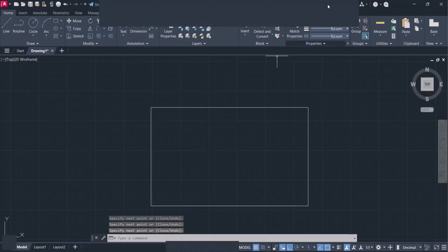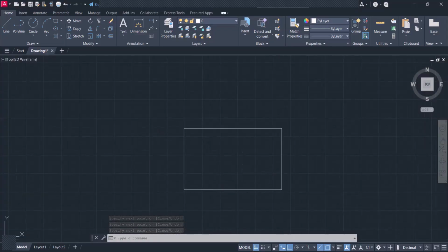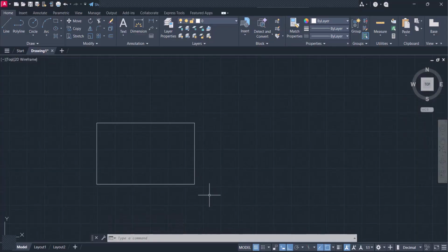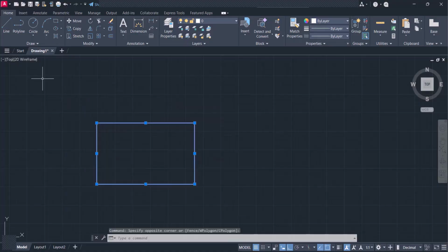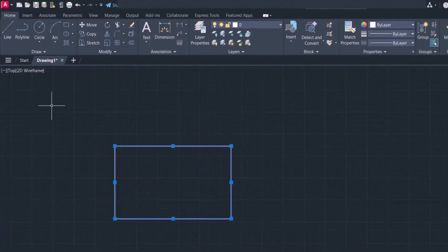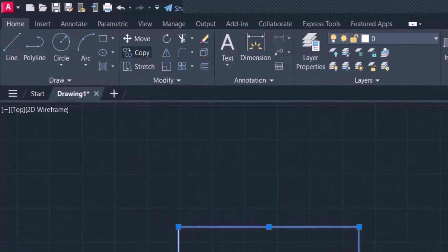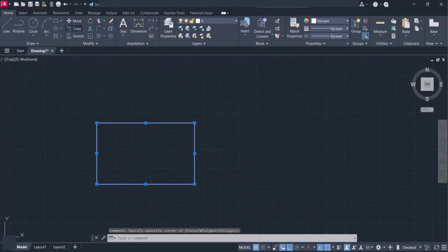So I'll need this rectangle twice, but instead of drawing it twice, we could just use the copy command. I'm going to left click here, then move my crosshair to cover the rectangle with this shaded green area, and left click again. Next I click on copy and select anywhere on the screen, but most likely I like selecting the edges of whatever line I'm copying.